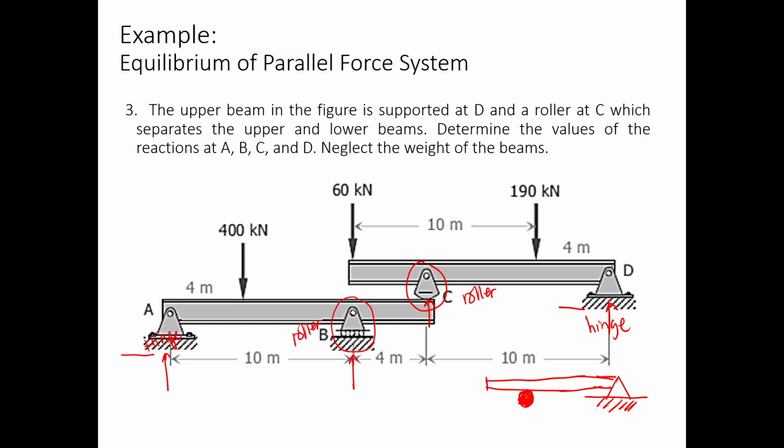So since we don't have any horizontal forces present in the system, as you notice, puro siya vertical load, all of which are vertical loads. So meaning we can declare that the horizontal component of the hinge supports are equal to 0. So if you're going to ask me when will that horizontal component be available, that's what we'll be discussing on Thursday.